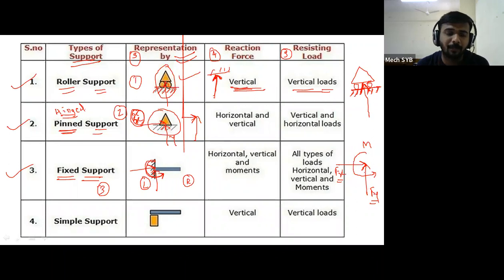जर एखाद्या बीमचं मुवमेंट स्वतःच्या ऍक्सिस भोवती जरी होत असेल आणि ते जर आपल्याला अवॉइड करायचे असेल, तर त्या ठिकाणी तशा बीम मध्ये हा फिक्स्ड सपोर्ट काय केला जातो, प्रोव्हाइड केला जातो. म्हणजे ह्या फिक्स्ड सपोर्ट मुळे काय होतं, हॉरिझॉन्टल मध्ये होणारं डिफॉर्मेशन पण रिस्ट्रिक्ट केलं जातं, व्हर्टिकल डायरेक्शन मध्ये होणार पण डिफॉर्मेशन रिस्ट्रिक्ट केलं जातं, आणि तो जर बीम त्याच्या स्वतःभोवती पण एखादी जर मुवमेंट होत असेल, तर दॅट इज ऑल्सो रिस्ट्रिक्टेड बाय दिस पर्टिक्युलर मुवमेंट.